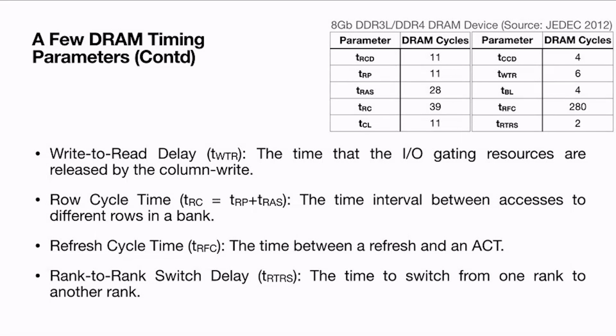So that's another motivating factor for us to keep servicing the requests from reads continuously, and then move to writes, and then perform writes continuously, and then move back to reads and so on, so that you can amortize this cost. Otherwise, if you're scheduling in a very bad way, first read, next write, read, write, read, write, every time you are going to incur an extra 6 cycles and so on. That's not a good idea.